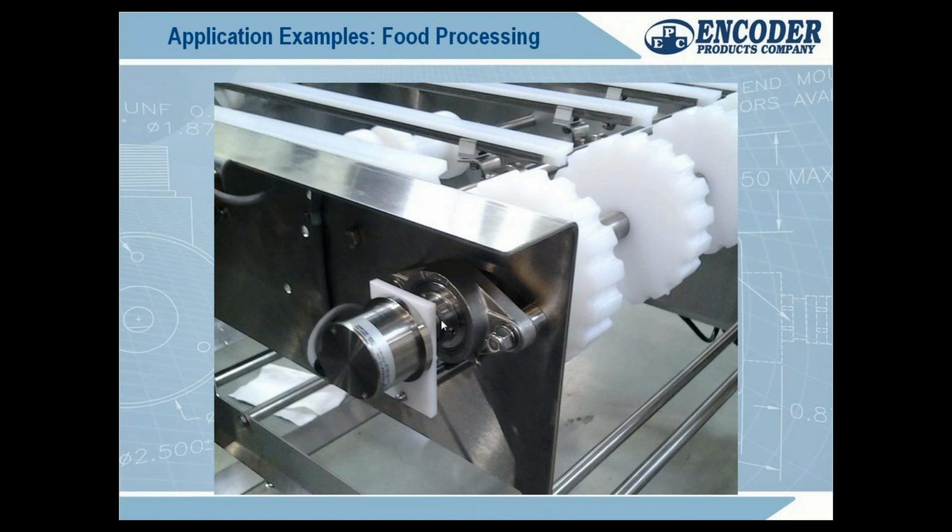Now, I don't recommend through bore encoders with a hole in them, because if this were a through bore on a shaft, you would have an exposed seal right here protecting that encoder, and the shaft would be coming out. When you have a washed out environment, that's just a great way to get pressure. I don't care what the rating is, IP69 even, they can still fail when they get pressure up against them. So just better safe than sorry from that preventative maintenance question.